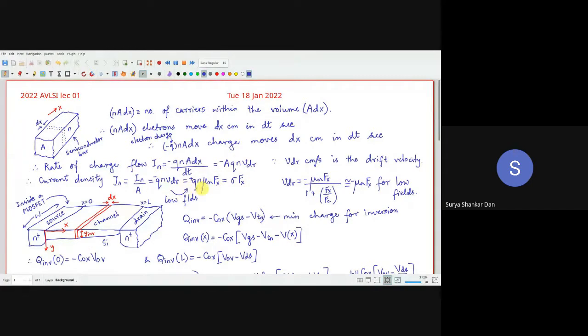So once you have got this Q n mu n, that is written as conductivity. Conductivity is equal to NQ mu n. There are also other parts for the holes. We don't need to bother about the holes because, can anybody tell me why am I not writing PQ mu P here? This part is missing. At least the ME micro students should be able to tell me. In PMMD, yes, please tell me. In the inversion, like minority